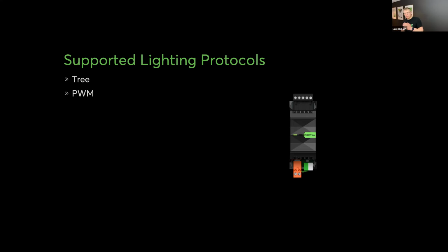So this means we could use the RGBW dimmer, and per output, it works at about £17 as opposed to £23, £24 from a relay. So again, quite a good cost saving there. You get a smoother dimming, but not only does the RGBW 24 volt dimmer support 24 volts, but also 12 volts. So quite a lot of flexibility there.